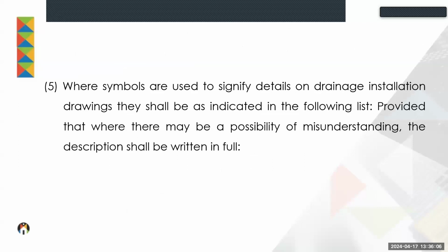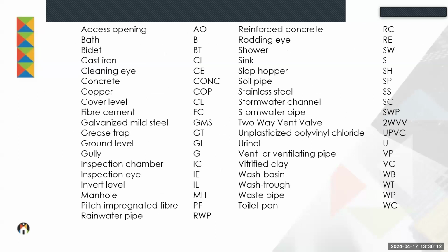There are specific symbols that we need to use on drainage installation plans. Don't make up your own. They are there as listed. They are in the regulation. And if there's any doubt that it might cause confusion, write it out.